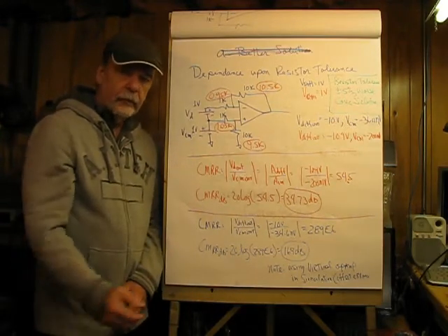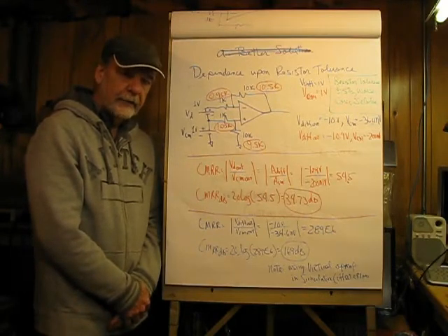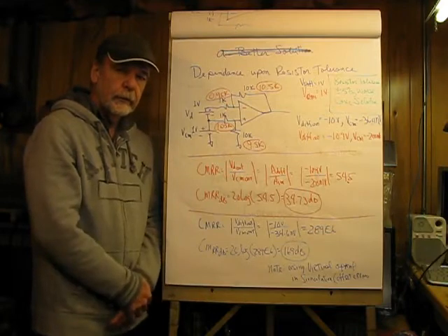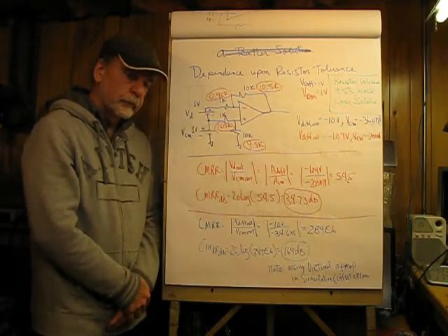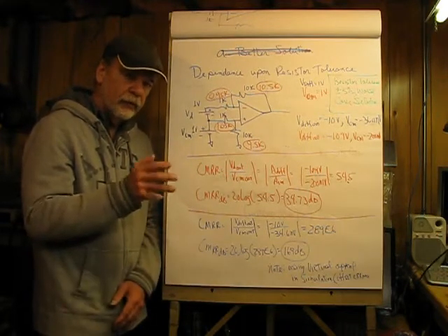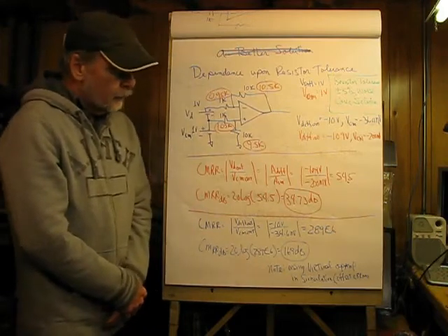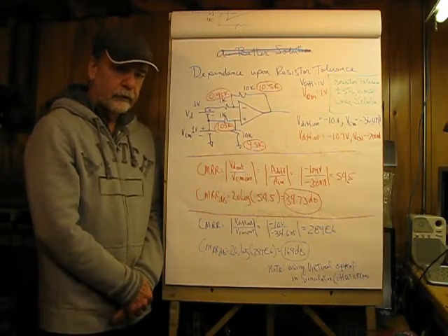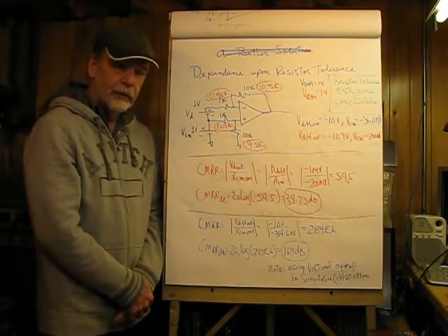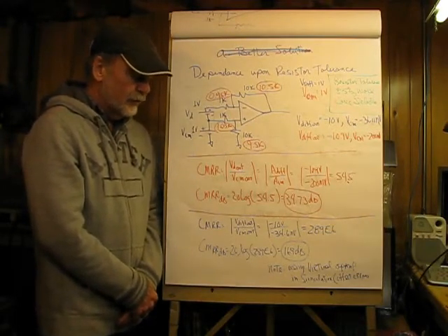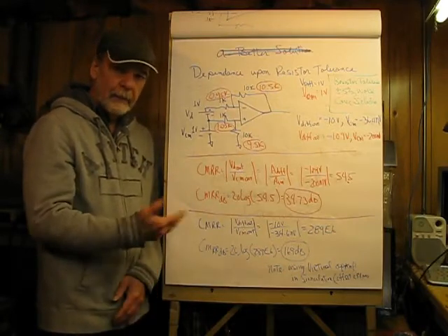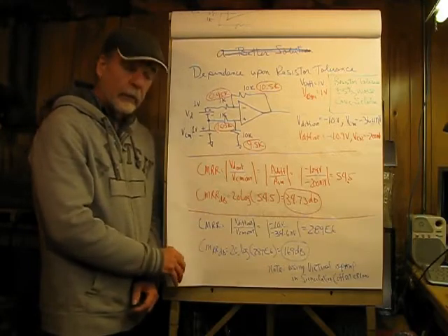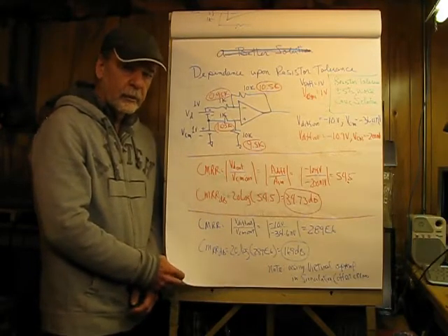I have a sensitive radio here, and if I want to listen to anything out of town on shortwave or AM, I have to turn the lights off. Now, these are CFLs, so they have ballast type of circuitry in them and so forth. So under that circumstance, where you're dealing with a very small differential voltage and a very large common mode voltage, the common mode rejection ratio is the parameter that makes or breaks the whole thing. And that's why, for that example, it really, really needs to be a good number.